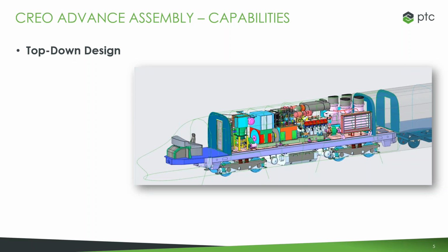So this is supported in a couple of ways. The first thing is the skeleton model. So the skeleton model is a model that allows you to plan the assembly framework using this tool to define the assembly structure. So what are the key pieces of geometry that define my assembly, right? And what is this going to look like? Where are my boundaries? So this would be something that the team or the lead engineer or someone would come up with and create the skeleton model.